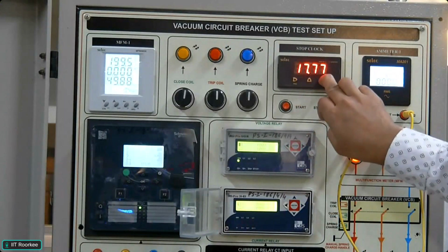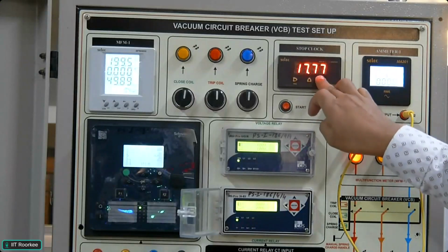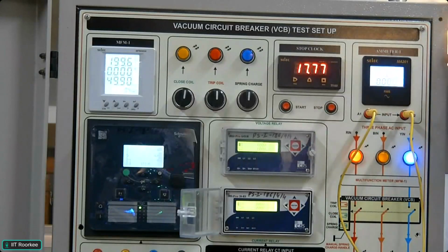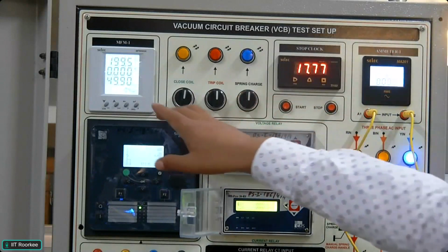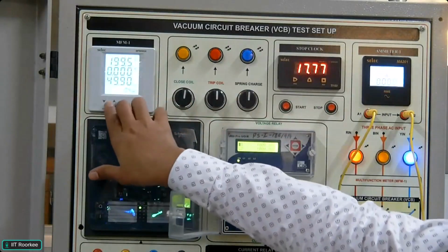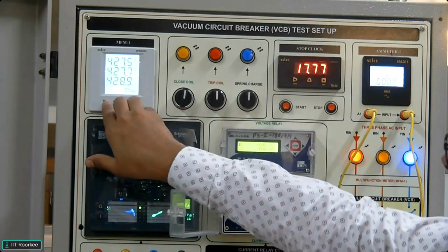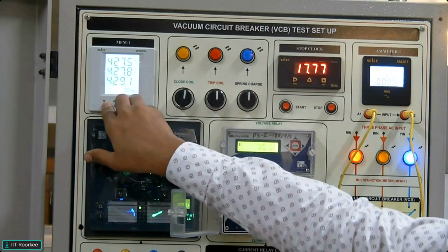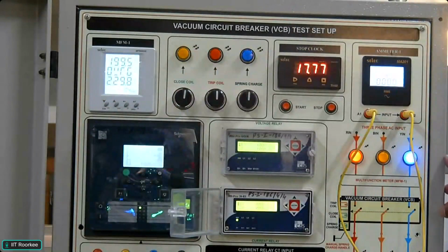So for 1 ampere, it took 17.77 seconds. The thing is that we turned on a load of only 1 ampere, but it was showing 1.23 ampere. That was coming due to the improper power supply. It means we are not getting 415 volt, but something like 427 volt. Due to the improper grounding of the supply, we are not getting the balance. That's why it was showing 1.23, so that's why the fault has occurred.